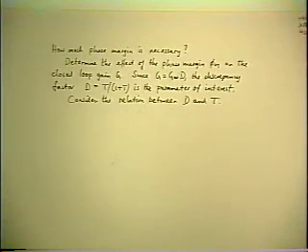What really matters is not simply is it stable, because it's stable even if there's only 1 degree of phase margin. What is more important is what is the response of the system relative to the specifications.